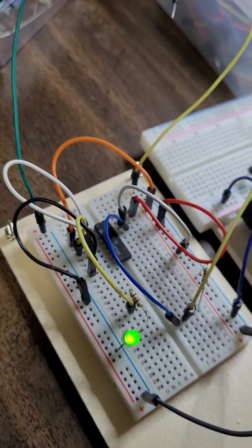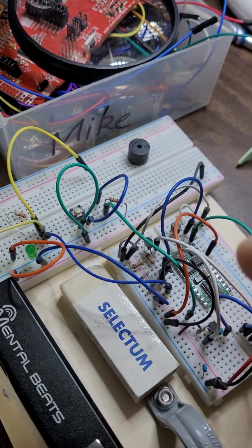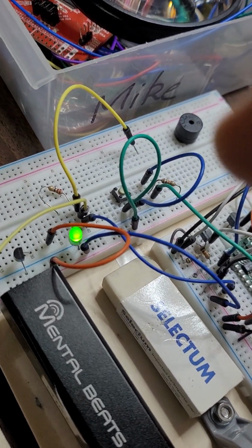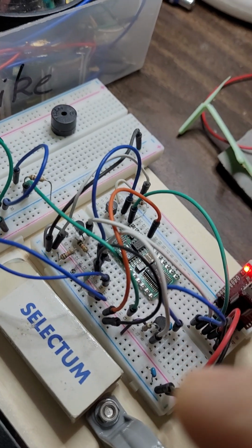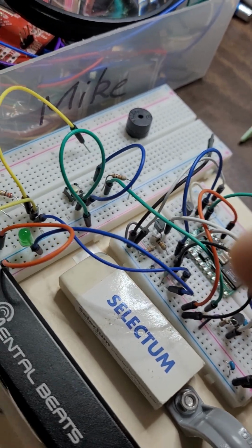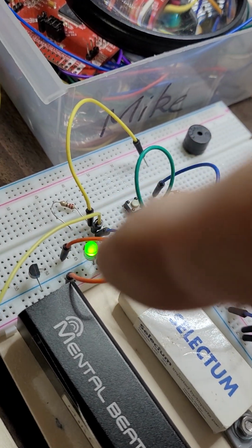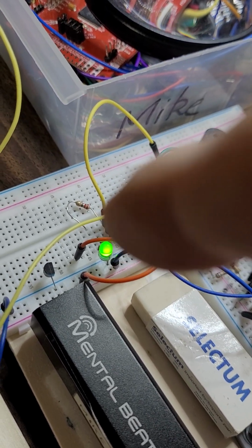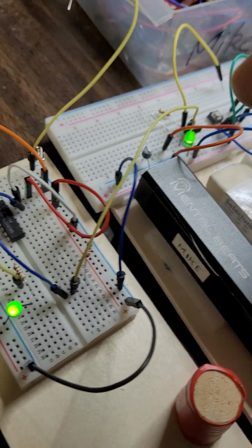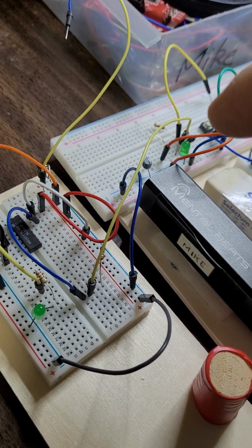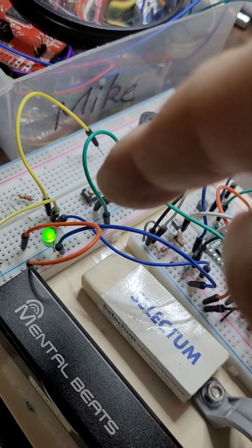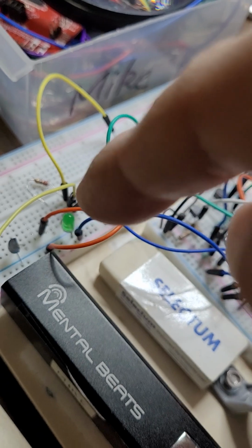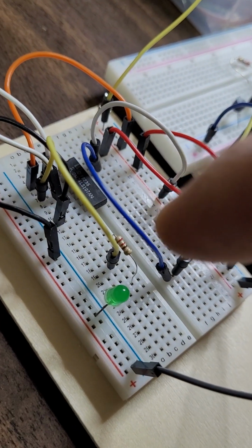Let me show you here what I am actually doing. This is another microcontroller; I'm just playing games here. I caused this microcontroller to provide me with a square wave with a cycle of a half second, or 500 milliseconds. As you see, I'm passing the output of this square wave clock with a cycle of half a second to the input of the JK flip-flop.